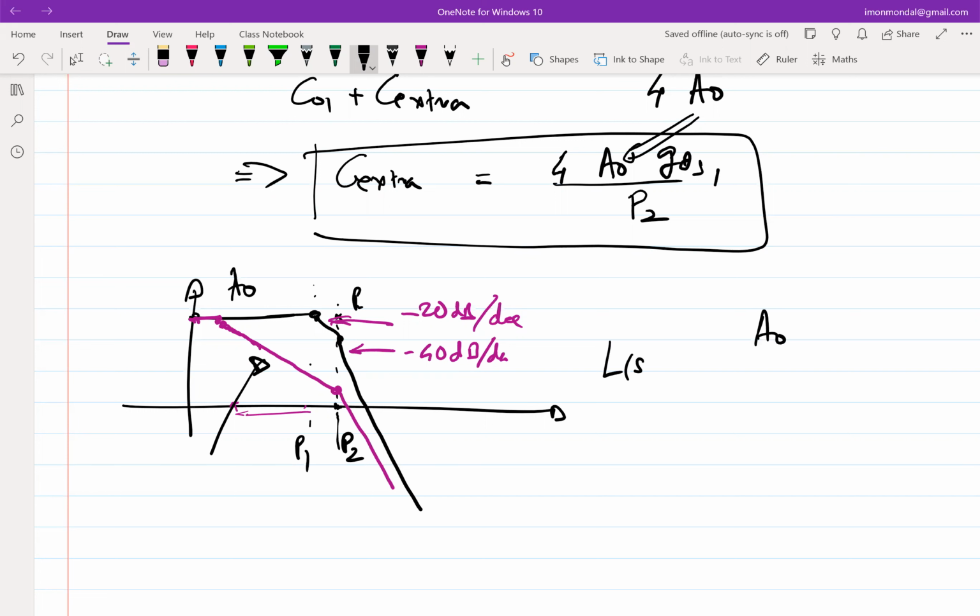One of the reasons why we want to get an integrator-like response is because if you have an integrator-like response around the unity gain frequency of the loop, your output settles like a first order system. I haven't proved this rigorously, but in the previous lecture we assumed that for a first order system, omega u loop is essentially 1 over the time constant of the closed loop system. So your integrator-like response around omega u loop is essential to ensure a proper settling of the output.